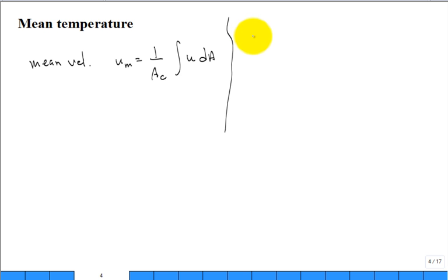So we're interested in a very simple expression for the rate of energy flow down the pipe. We'd just like to use the mass flow rate, the specific heat, and some representative temperature, the mean temperature. But we know that the fluid is flowing faster in the middle, and it may be lower temperature or higher temperature in the middle.